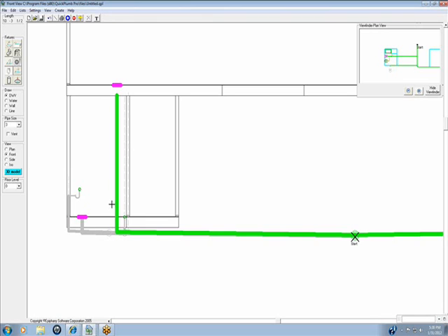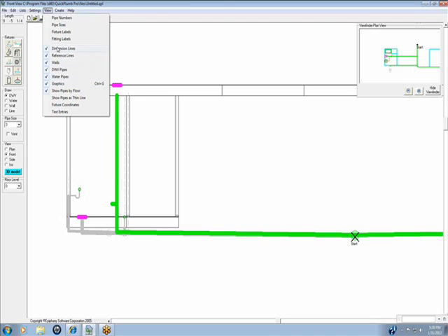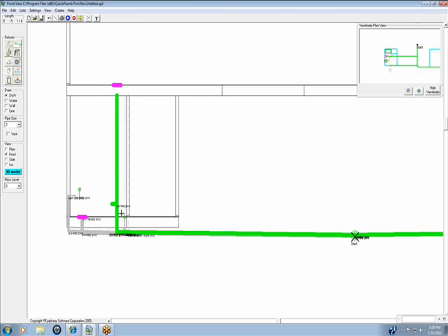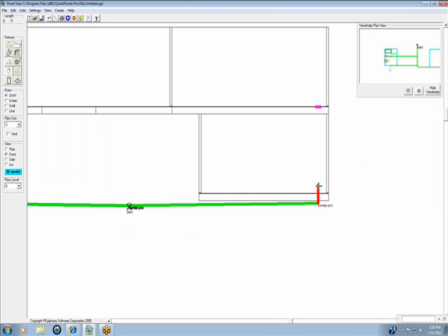I'll bring it up, and I'll put a little clean out tee down here. As long as it's a short piece of pipe, it'll consider that a clean out tee, and I can verify that by going to fitting labels. If this pipe here is longer than 8 inches, it calls it a sanitary tee. If it's short, it's a clean out tee. And that takes care of that one. Now I'll extend this pipe up, put a little clean out tee here,